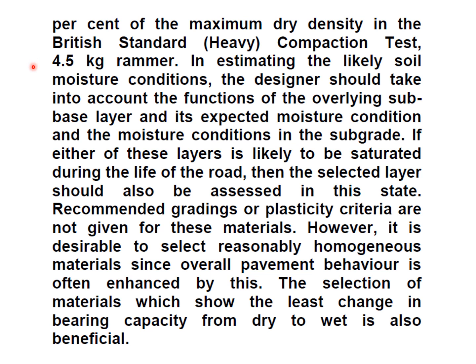In estimating the likely soil moisture conditions, the designer should take into account the functions of the overlying subbase layer and its expected moisture condition, and the moisture condition in the subgrade. If either of these layers is likely to be saturated during the life of the road, then the selected layer should also be assessed in this state.